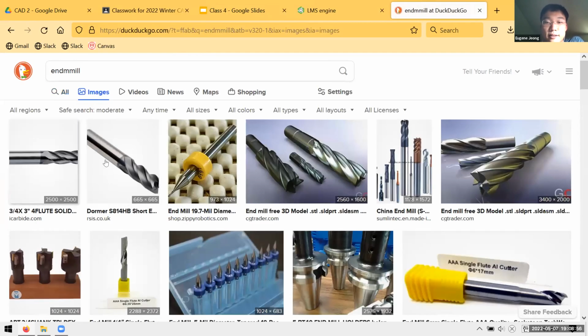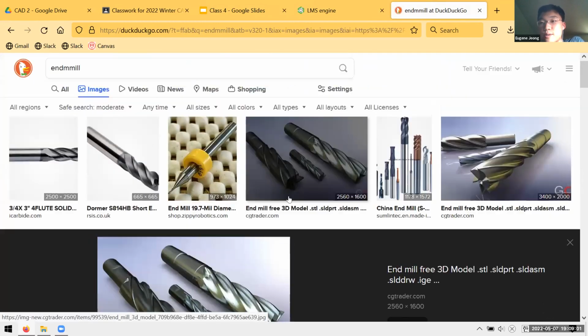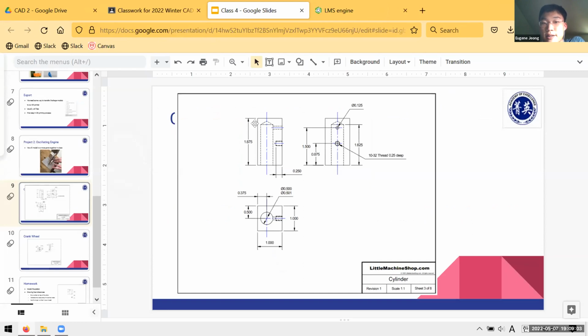And sometimes it can require a CNC operation. You need to use more complex tools to create blind holes that have flat bottoms. So in our case, we can just completely ignore all of that. We can either use a tool that I'm going to introduce called the hole tool, which allows you to model these things automatically, or you can just ignore them, and either way, it's going to amount to the same thing.